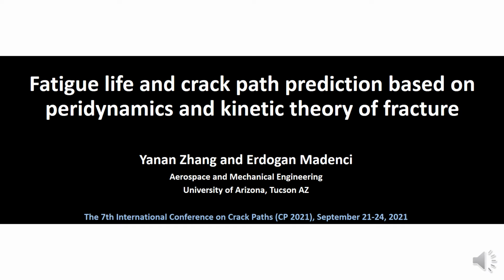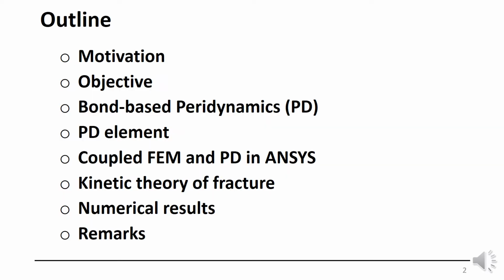I'm going to talk about fatigue life and crack path prediction based on peridynamics and kinetic theory of fracture. So here's the outline. I'm going to briefly go over motivation, objectives, describe bond-based peridynamics, peridynamic element, how we couple peridynamics with finite element and ANSYS framework, and briefly describe kinetic theory of fracture, and then show you some numerical results and end my presentation with remarks.